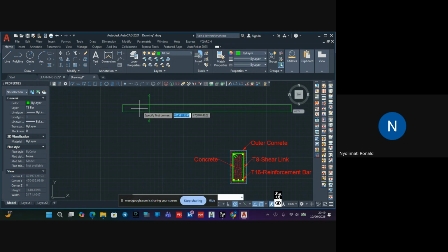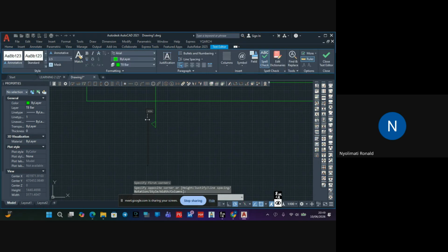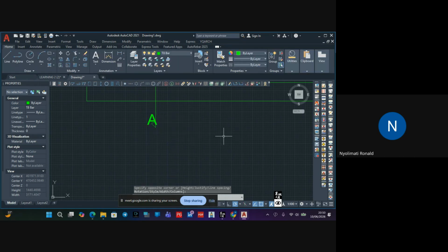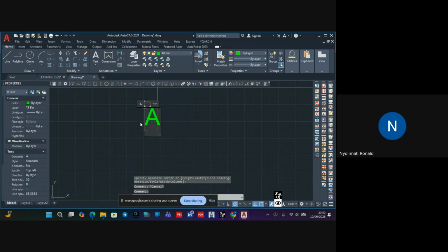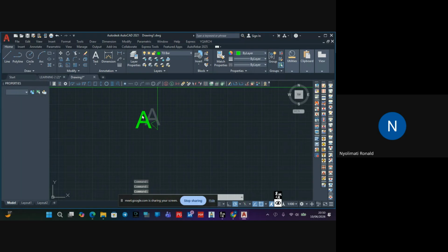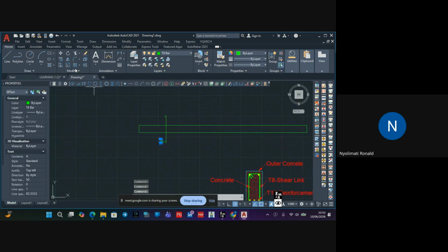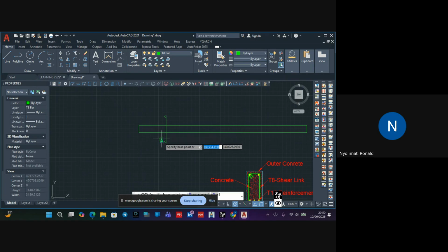Okay. So if you wanted this section, you go to text and click here, text height. That section is called AA. Just change the text height there to 50, enter. Click here. All of this section of the beam you're seeing here, it is AA. Here, you copy this, take it up. Also A here.